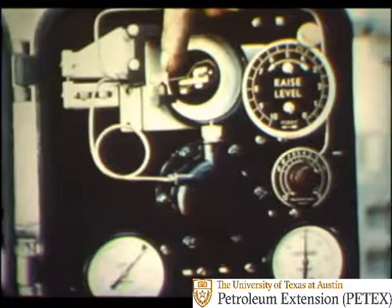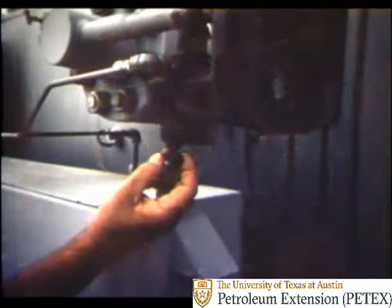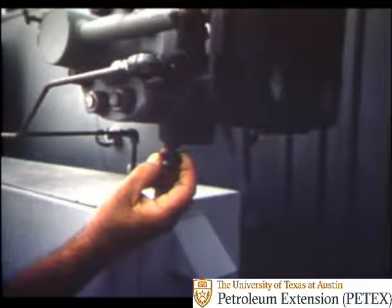The operator may stroke the control valve by carefully holding the flapper on the nozzle or by lifting it off with his finger. By this method, you will not disturb the set control point preset in the controller. Then we saw the supply air regulator. Each day, open the petcock to bleed any water that may have collected in the regulator.